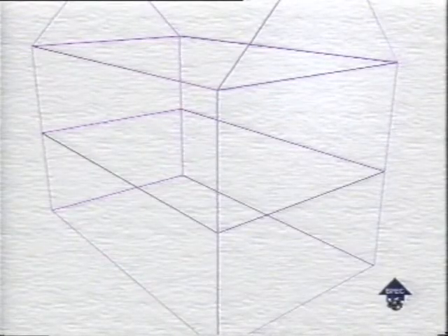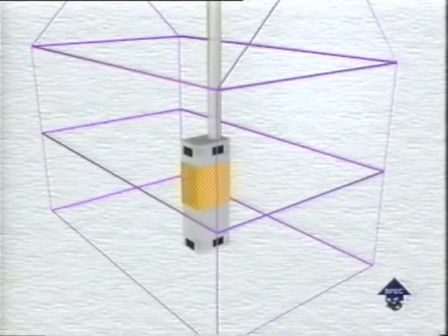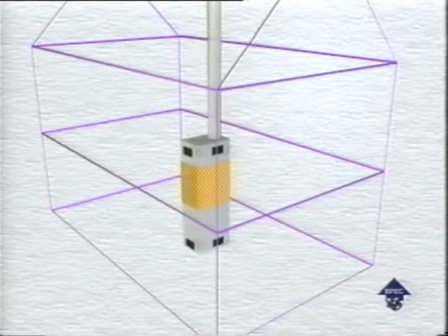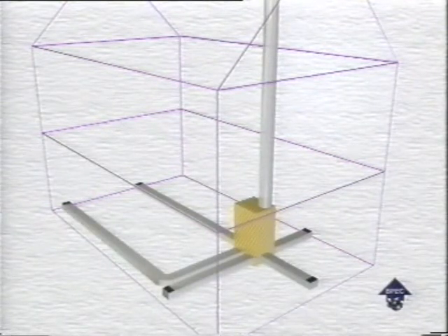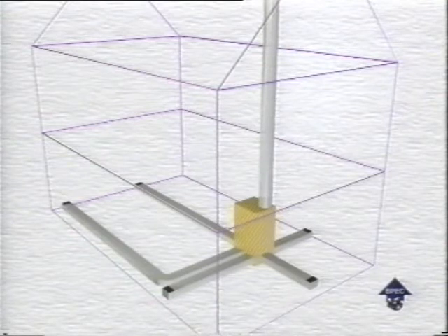There are different methods of distributing the air. This is a stub duct. It's the sort of system you'll find in small houses and flats heating just 2 or 3 rooms. This radial arrangement has ducts branching directly from the chamber that holds the warmed air, known as the plenum. The branches shouldn't be longer than 6 meters.